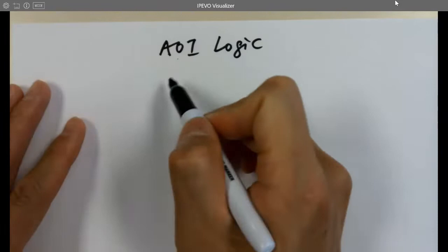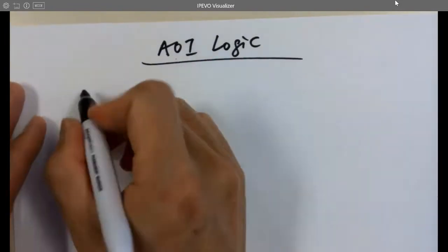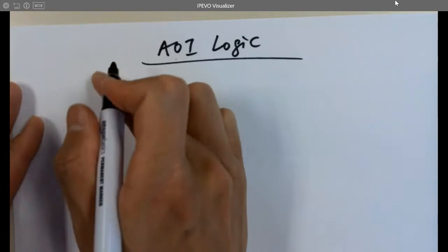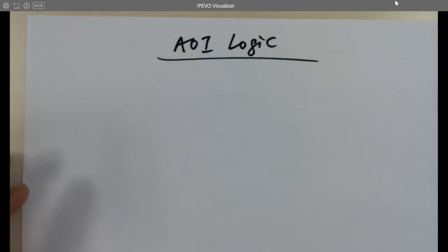And the inverter. It has the PMOS on the top and the NMOS at the bottom, and the logic has a bar on the top. Why? Because when you turn on the PMOS, the input is 0, but the PMOS shorts the output to 1. So I have 0 as the input, but the output is being pulled up to VDD, so it's a 1 there. Right, so I have to invert it in order to get the right logic.